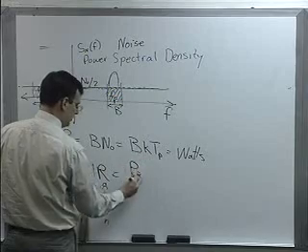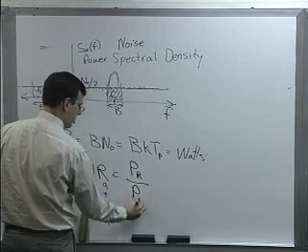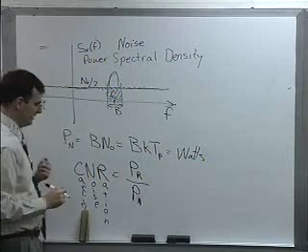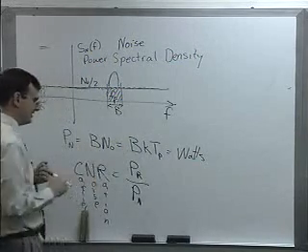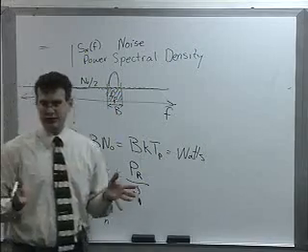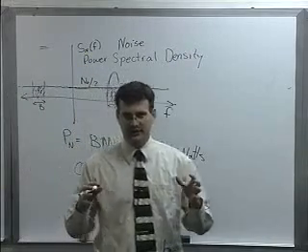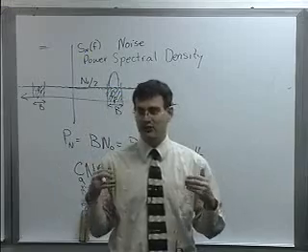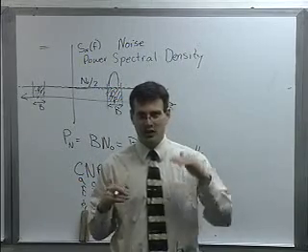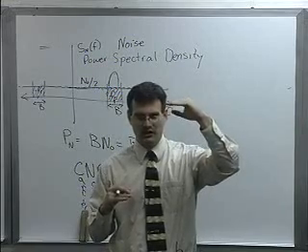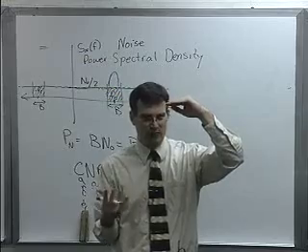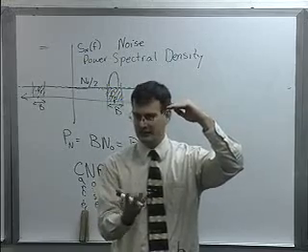You take your received power, you divide it by your noise power, BKT, or KTB. Usually put Boltzmann's constant first. And this also often tells you the fundamental limit with which you can transmit information, because it's basically a measure of the quality of your signal power and the disturbing noise that's going to corrupt it and keep you from decoding that signal.